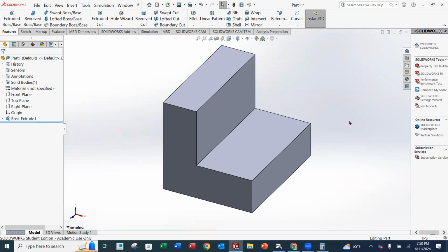Now, yes? How do I get rid of this new shadow that's here? Yeah, so if you go to view settings, I think it's shadows in shaded mode. You can toggle that on or off. Did it go off for you? Okay, yeah. There's a couple little settings over here. You can change colors, you can change the backgrounds, all that kind of stuff. I saved that for later. But yeah, that's one of them. It depends on what the settings were when they put the image on.